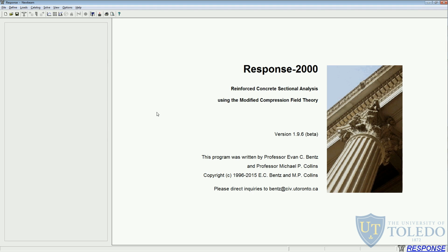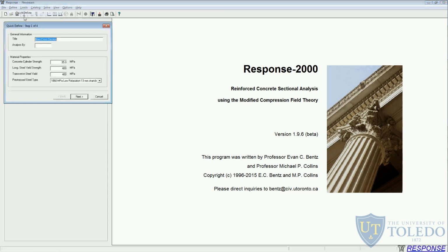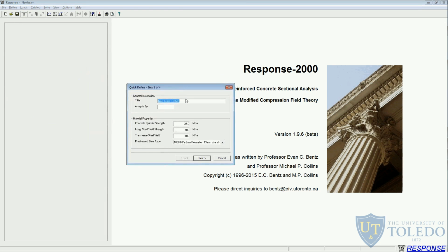So the first thing you want to do is come here to Define, Quick Define. And here Response 2000 lets you give a name for your analysis. I'll just call this video 2. And here it asks us for some basic material properties that will be present in our cross section.